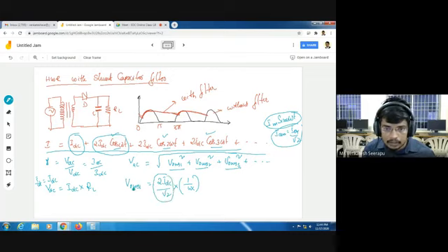All of you know that VRMS can be calculated as IRMS into the resistance value. Here we have two resistances: the capacitive reactance of the capacitor, and the resistance value. Compared to C, we can neglect the resistance value. That's why I neglected this value. I have written IRMS into this resistance as 1 by omega C. Similarly, what is the VRMS2 value?